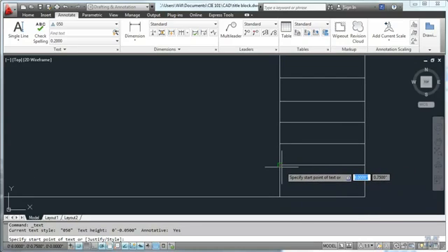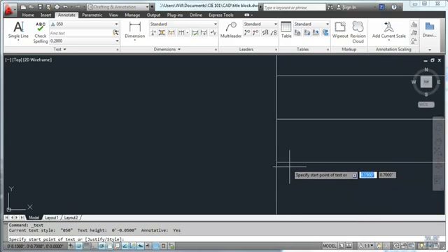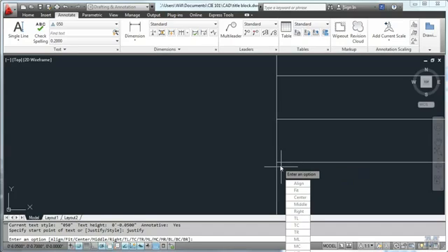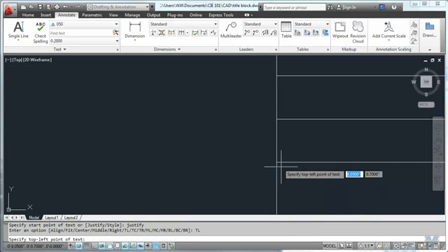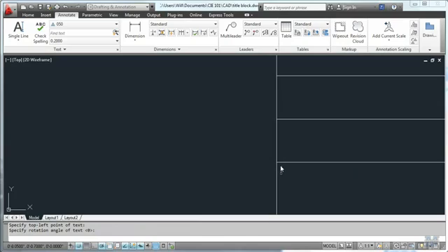We're going to label all these little spots. So we'll zoom in a little bit, and this is where that 0.05 clicking comes in nicely. We're using this style, and I'm going to make it justify. Just type in justify, and I'm going to use top left. So that's where the top left point of text is going to be. I'll left click right there, rotation 0, and we're going to call this the drawing number, right?